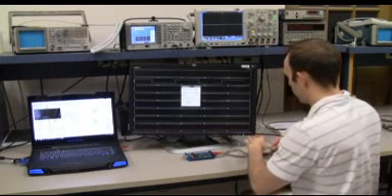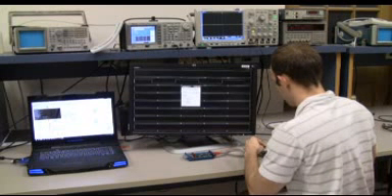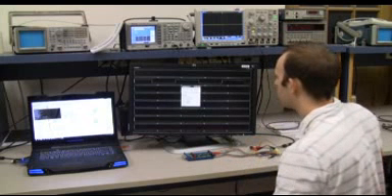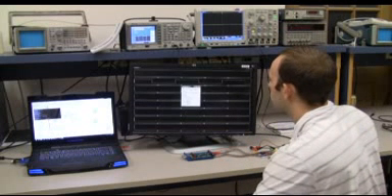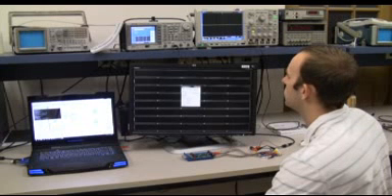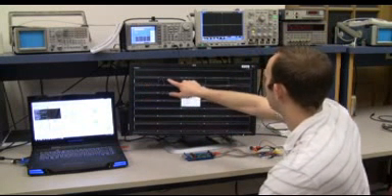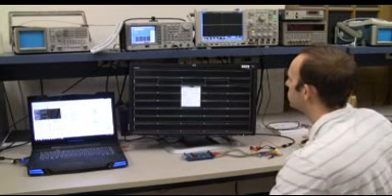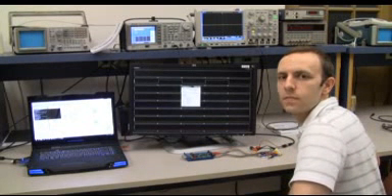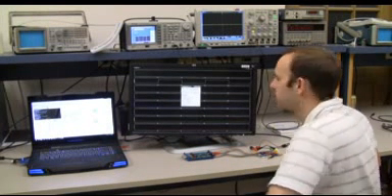We can use a falling edge control signal, which we will be using channel 3. Set channel 3 to 5 volts, and go. And as you can see, it was captured on the falling edge, low, then high. That should prove functionality for the Logic Analyzer.